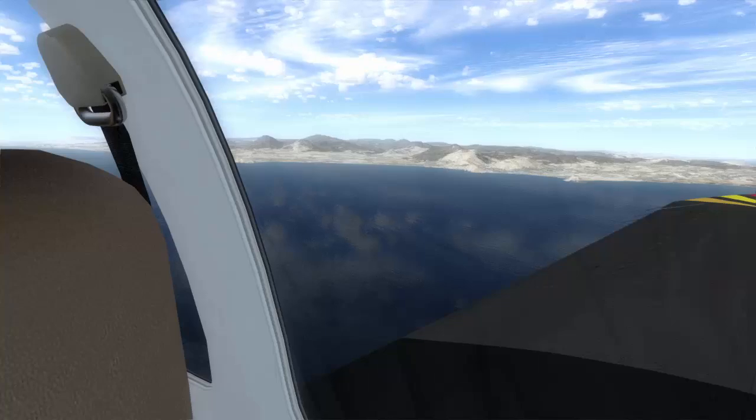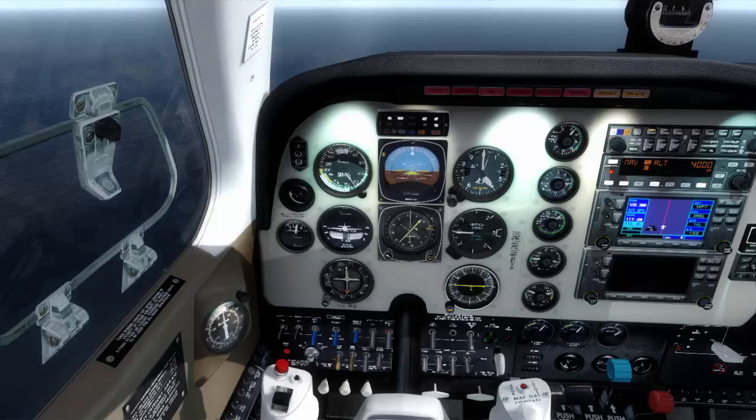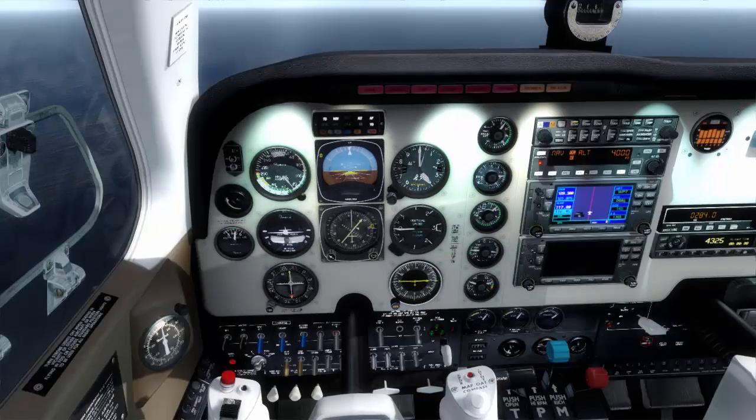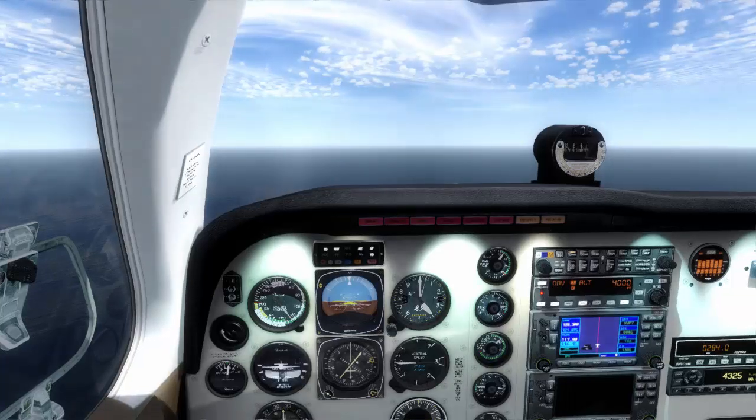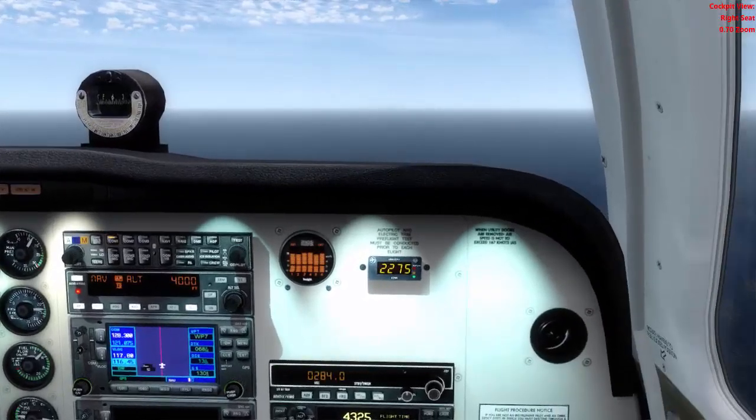And how much must you descend? How do you program that descent rate? According to the recommended landing speed of your aircraft, we will have tables in our charts, exactly in our instrument approach chart, and that table will guide us about how much we have to descend this bird.